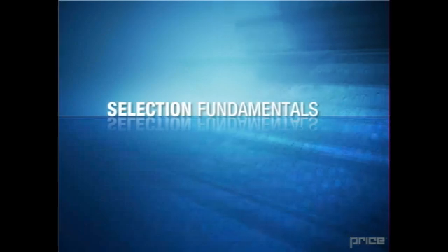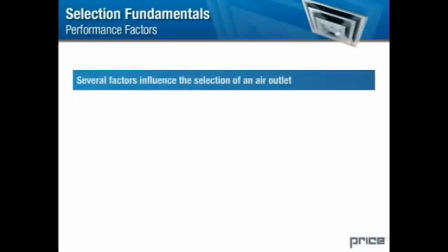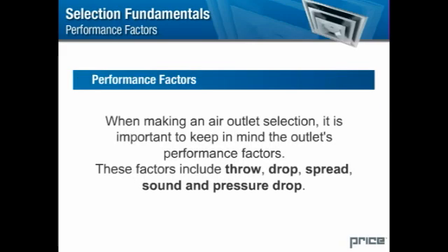Selection fundamentals. Performance factors. Several factors influence the selection of an air outlet. These factors can be divided into two groups: performance factors and design factors. When making an air outlet selection, it's important to keep in mind the outlet's performance factors. These factors include throw, drop, spread, sound, and pressure drop.